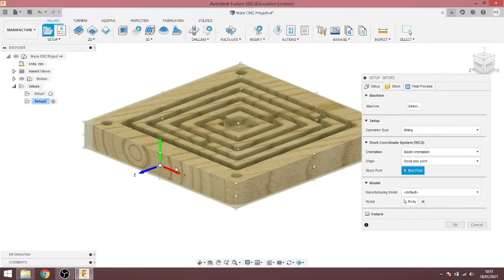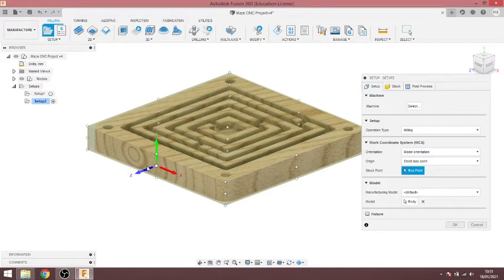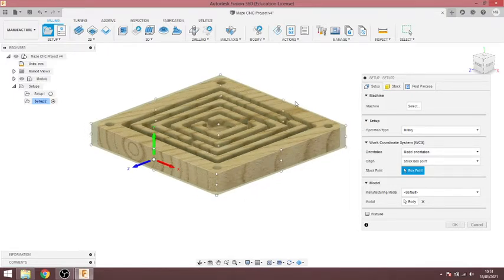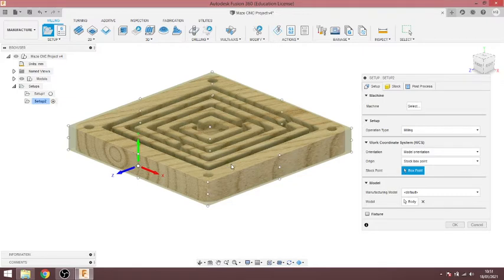Now the Z axis you don't want facing in that direction, because the cutting tool on your CNC router is going to be moving in a vertical plane, so that is going to be coming down and cutting these pockets out. So we need to change this, and we also want to change this stock material size that's preset.